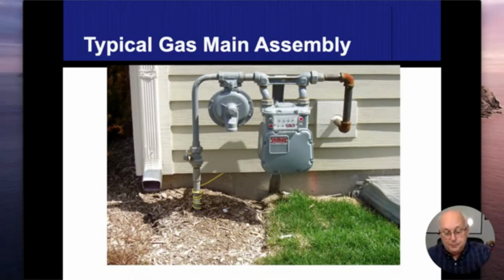So we come back in, 4 psi, the pressure reducing regulator will lower it down to 1/4 of 1 psi. Then it comes to our gas meter. These dials on the gas meter is what I was talking about. You time as those go around when you do the gas timing chart. And again, you can find that up on our website. And then it comes up through here and then into the house and comes forth.